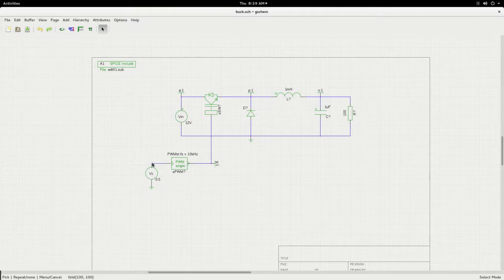So if you look at the gate drive node here, you will get the pulse width modulated signals, which will be controlling the on-off of this, and how the power gets pumped into the inductor and the output capacitors of the load.